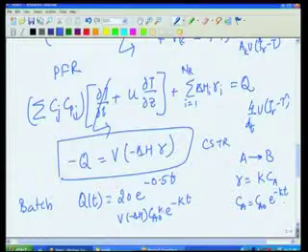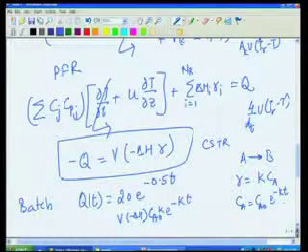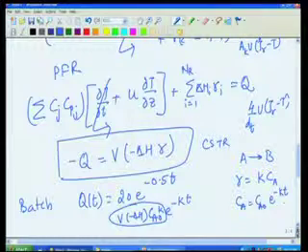For a batch reactor, assuming all this is constant, with a k value of an arbitrary 0.5, it means that to operate a batch stirred tank reactor in an isothermal manner, I have to remove energy in an exponential manner. Why? Because the rate of reaction for a first order system decreases exponentially, so my energy removal also has to be exponential.